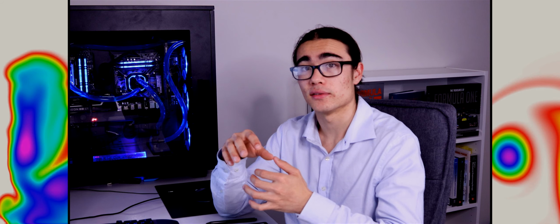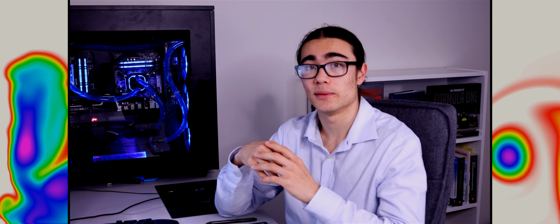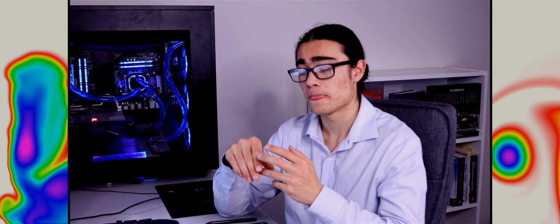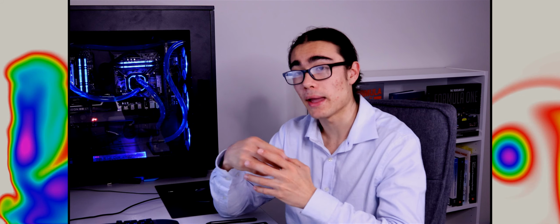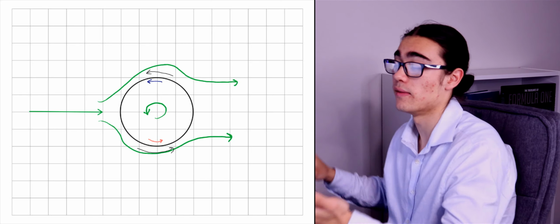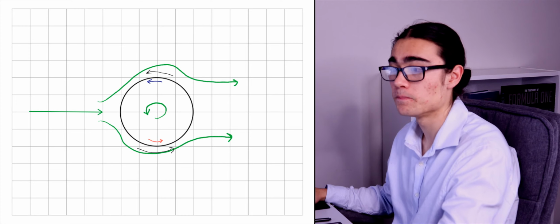When anything has viscosity and you rotate with a no slip condition, you're going to naturally affect the outer field. So if you have a jar of honey and you turn it in the middle, or something like paint, you'll still notice that the outer edges are still moving even though you're just touching the central part, and that's because we have viscosity.